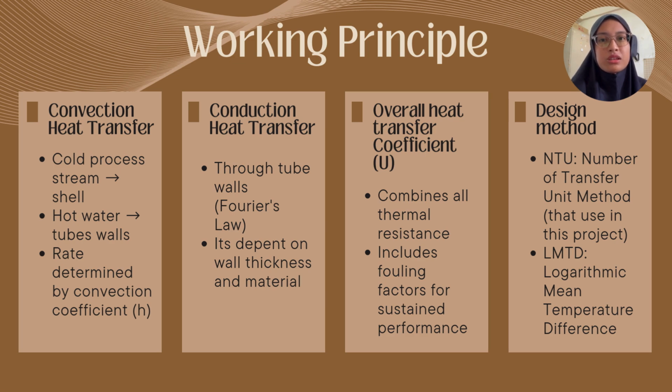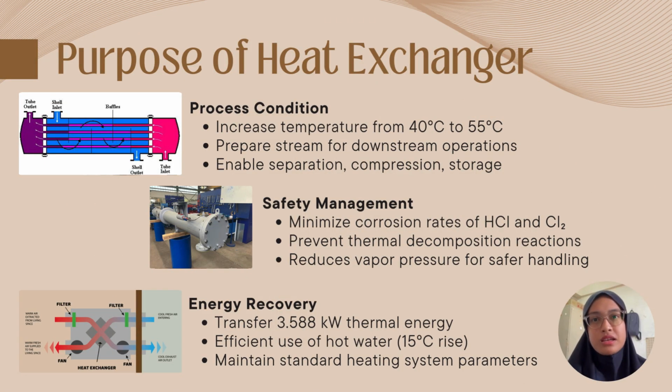For the design method, we use both the NTU method and the LMTD method to analyze and size the heat exchanger accurately. The purpose of this heat exchanger can be divided into three main aspects. First is the process condition. The heat exchanger increases the process temperature from 40 degrees Celsius to 55 degrees Celsius, preparing the stream for downstream operations such as separation, compression, and also storage.